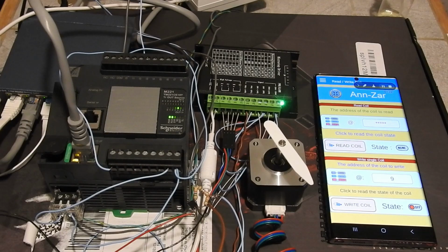In the program, every time the fast counter reaches the specified number of steps, it will stop the pulse generator and reset its own value to 0. Then, when the motor has stopped, and you click the button again, the motor will make the same number of steps again and stop once more.